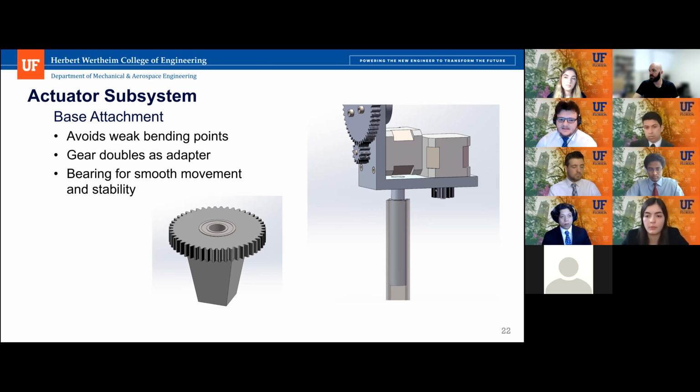Within that, it houses a bearing that fills that small gap you can see on the right between the mounting bracket and the transparent portion of the frame, which allows the housed metal rod you can see to translate all the forces directly from the bracket down to the frame without interfering with the gears or the motor shafts. It also makes sure it's a rigid object, therefore everything acts smoothly and rotates stably. We can move on to the next slide.